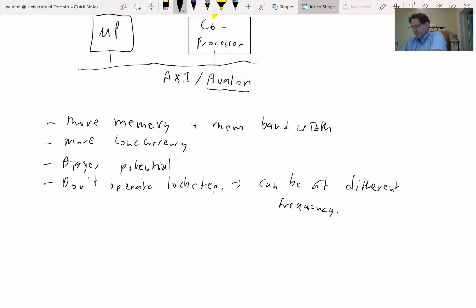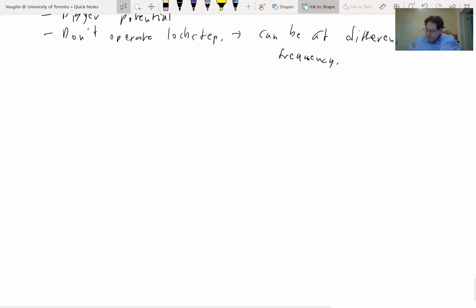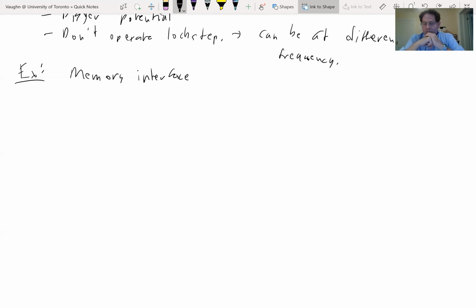Okay. So this is an example that came from a particular project in my career at Altera. I'm going to go through how we attacked developing a very complicated IP core for memory interfaces. Memory interfaces are basically DDR. There's DDR, then DDR2, then DDR3, then DDR4. They're all very, very similar. They change the electrical specs a little, they change the protocol a very small amount, but they just keep getting faster and faster, okay?